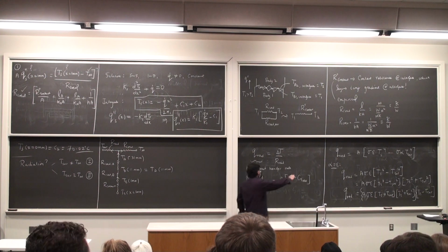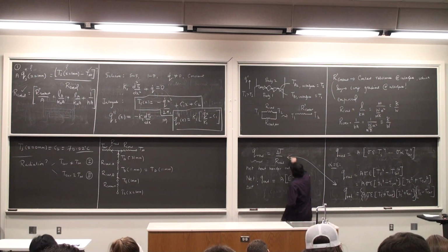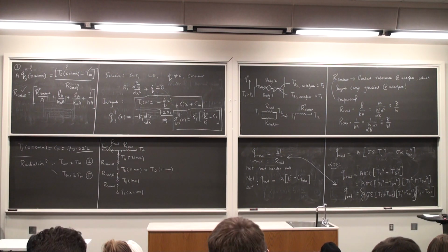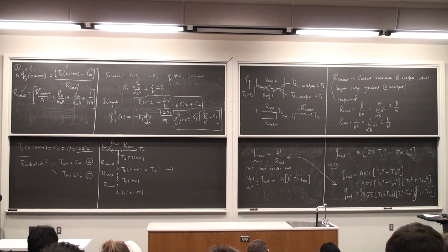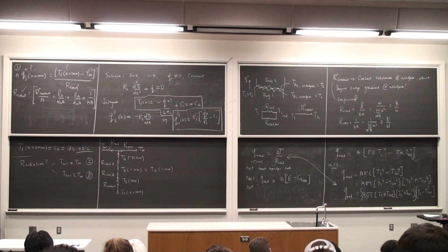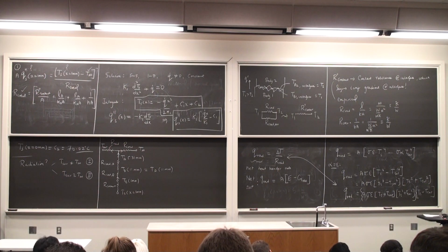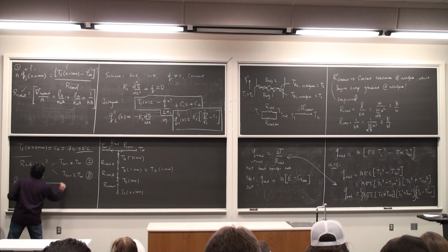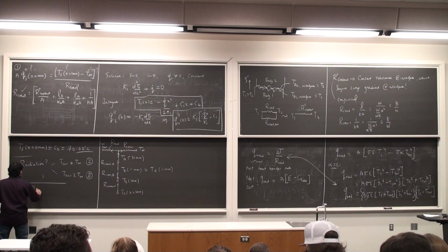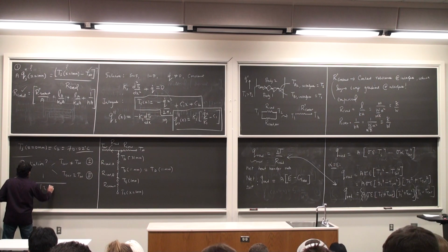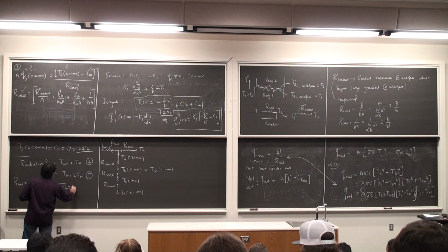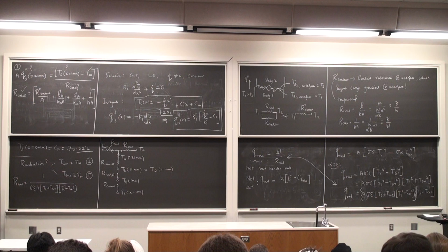Now, if I compare the two, what is my delta T? Delta T is Ts minus T surrounding. And all of that big thing that I've written there, the inverse of that is going to be my thermal resistance to radiation. Okay? So R radiation is going to be 1 by sigma epsilon A, Ts plus T surrounding, Ts square plus T surrounding square, which means that this is a problem.